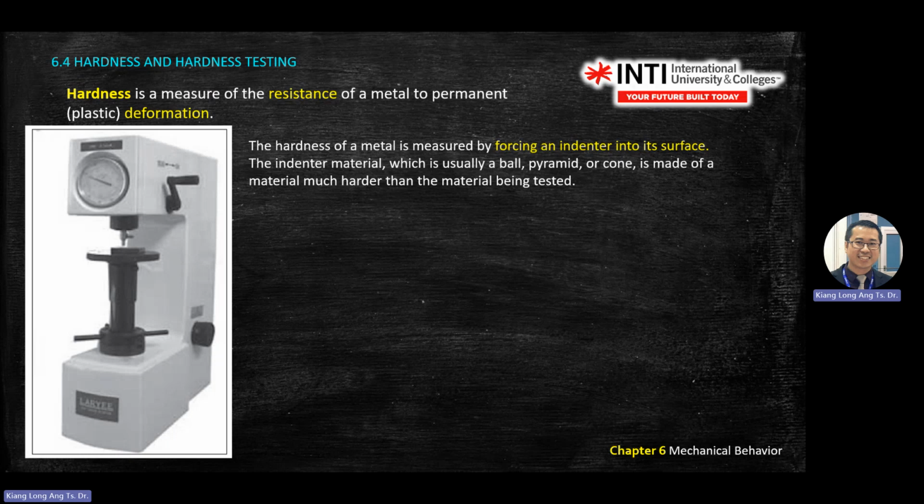You do the same, you press with the same force, let's say 100 Newton. When you have a stronger material, do you see the same size? It should be smaller, because it's harder to penetrate. It's harder to squeeze the material out. So you'll get a smaller shape, and the depth is also different.